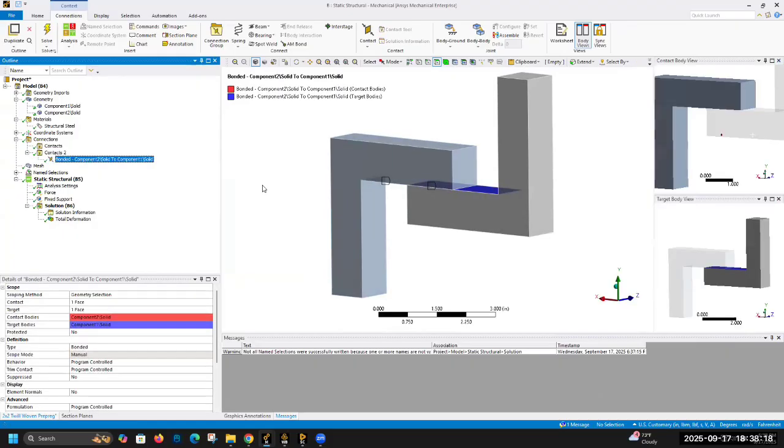Yeah, I think it's cool seeing that most contacts you're putting on this geometry will not solve. It may seem like some of them genuinely should, and it's confusing as to why it's not solving, but it shows how common pivot errors are. A lot of people resort to just saying, I'm having a pivot error, I'm just going to fix my part, which is not always conservative and not always true to what your part is. So sometimes it's really hard to get the contact to work. It's important to think through what's happening.